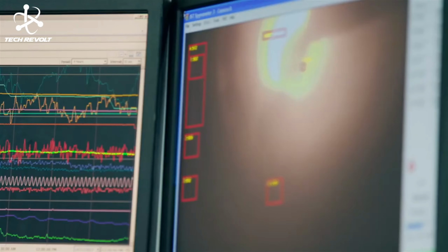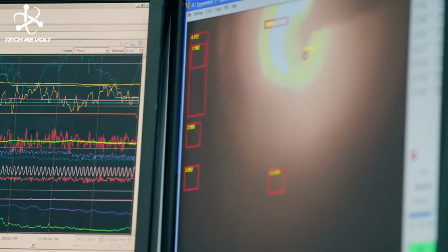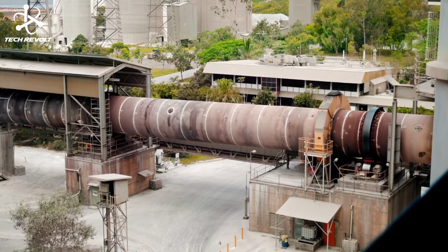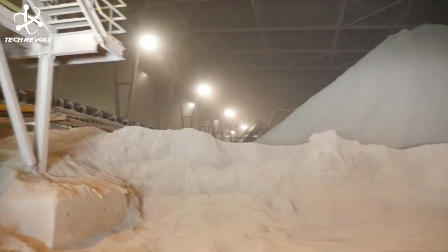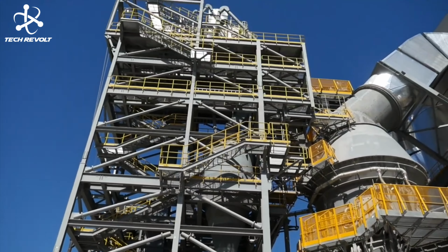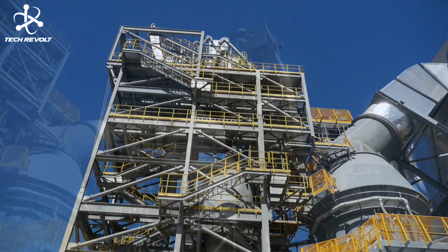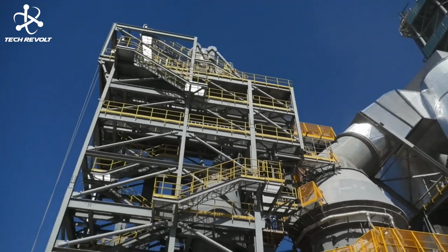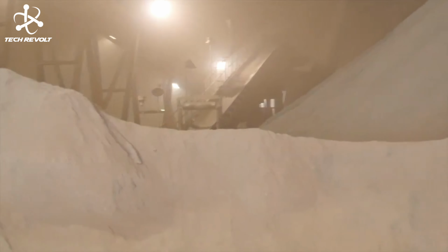Finer control is achieved by drawing material from 2 or more batches containing raw mixes of slightly different composition. In the dry process, these mixes are stored in silos. Slurry tanks are used in the wet process. Quality control experts constantly test this mixture to ensure it has exactly the right balance of ingredients.